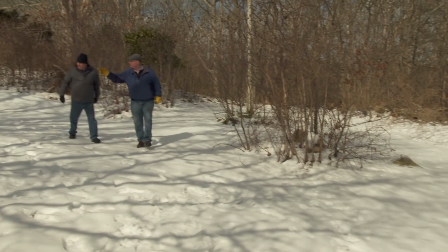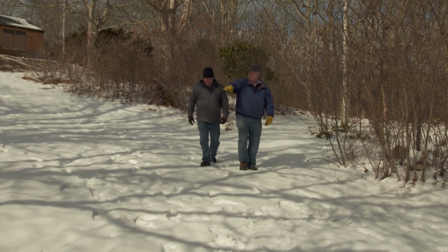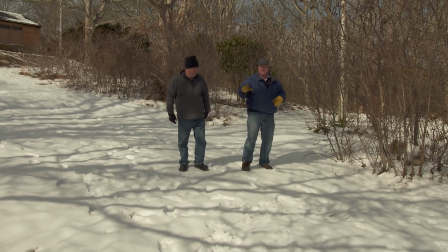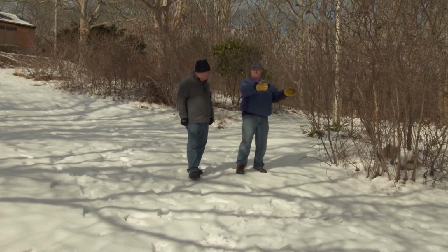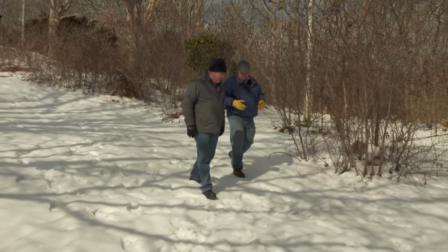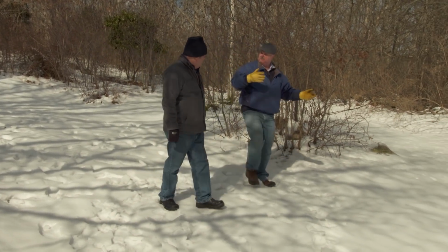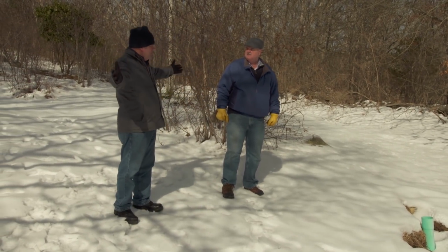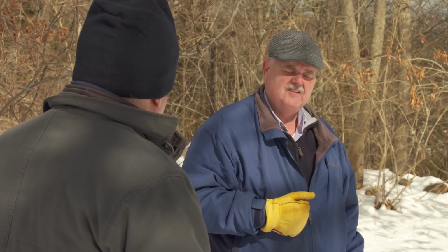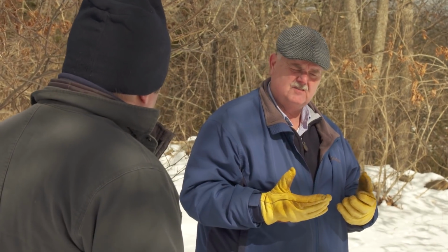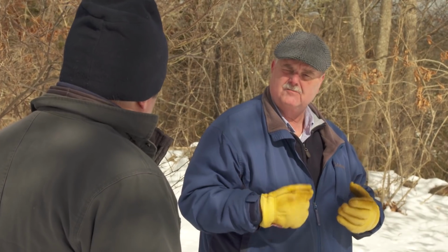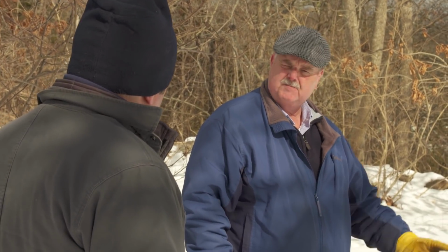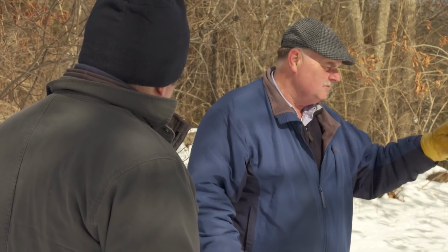Okay, the effluent will come down from the septic tank and it'll come down into a small pump chamber here. Right about here, okay. And then from here, it's going to get pumped up to the disposal field or the bottomless sand filter. Okay. The bottomless sand filter is about 10.5 feet by 20 feet. Now that's amazing. I mean, a typical leaching field is 30 by 60, 70, 80. This is really small. Yeah. No, one of the advantages of these types of systems is they're very small and compact. Yeah. That's why we use them. Great. The system's partially above ground, as I said, and there's going to be timbers around the edge and there'll be stone on top. That's all you'll see. Landscape around it a little bit? You can landscape around it to hide some of the timbers if you'd like.